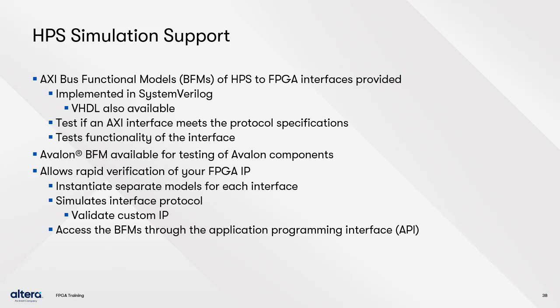Bus functional models allow for easy simulation of components by abstracting away the signals of the interfaces and allowing you to issue commands and responses to a design under test through a software-like application programming interface. You can use the BFM to see if an interface conforms to the protocol specifications, as well as to test the functionality of the interface.